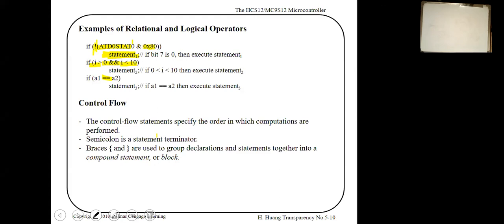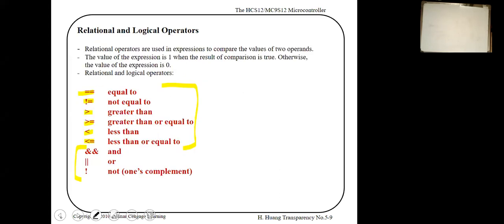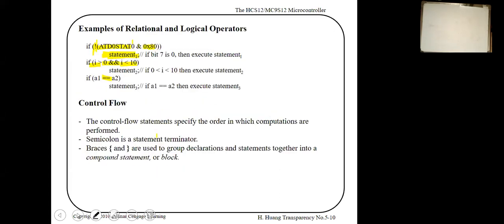Of course, yes. For example, Amal is asking whether all the IO pins are defined in the include file, yes. For example, this register is the A to D status register. It is already defined in the include file, so I am referring to it by name instead of by address.